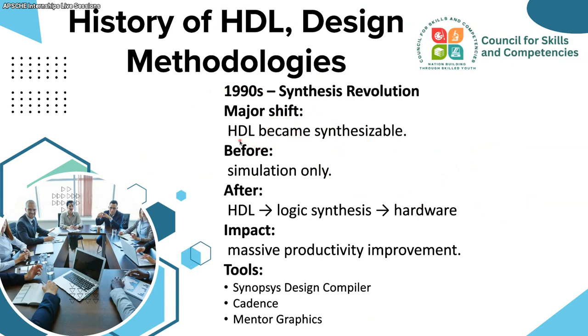So the major shift in the 1990s was that hardware description languages became synthesizable. Before that, we could only see simulation. Now we can check the simulation using the language itself, design for the hardware, realize it, and synthesize it. After that, HDL used logic synthesizers, and you can easily convert it into hardware.